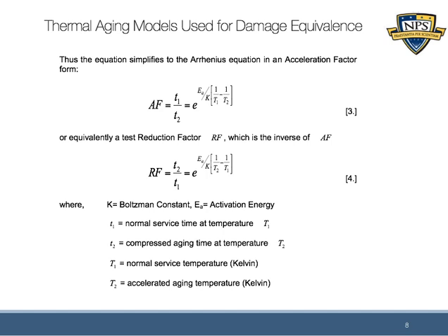So we can think about a component that would live for so long, and at some point, maybe would have a failure as a result of one of these failure mechanisms. And the question might be, how can we accelerate in a testing environment the precipitation of that failure mechanism?